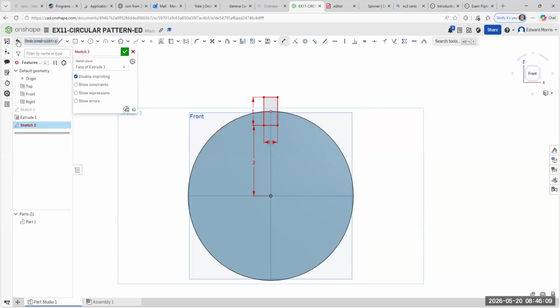So I'm going to undo that, watch. I'm not going to put that dimension there at all. I'm going to leave it alone. I'm going to put just a dimension here. Make that 2, enter, okay? Tell me when you got that. Because if you lock that into 1 inch, it's locked, and if you try to put that dimension there and edit, it won't let you do it. That's why when you see red like that, there's a problem.